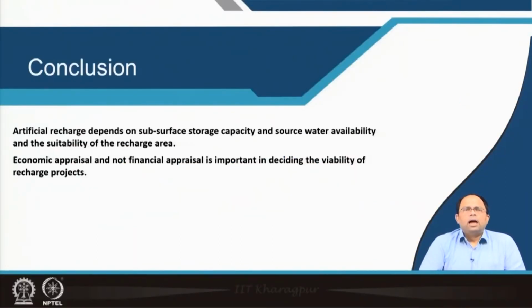So to conclude, artificial recharge depends on subsurface storage capacity, source water availability, and the suitability of the recharge areas. All these things need to be considered before we start any kind of artificial recharge project. And economic appraisal, and not financial appraisal, is important in deciding the viability of recharge projects.